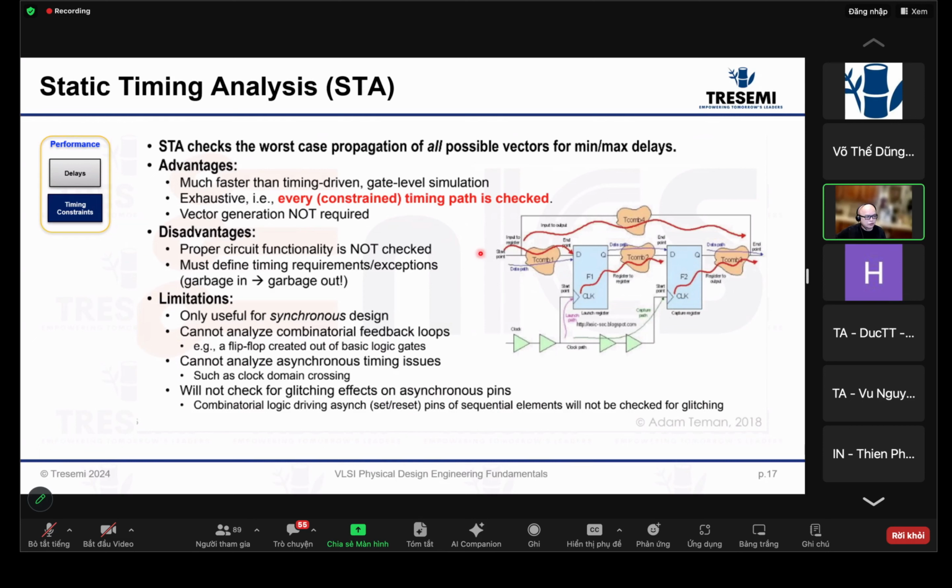So it's very important to check the quality of the constraints going in. While we said it is the most complete, as I mentioned, there are different behaviors that need to be checked by, say, dynamic simulations, and all the asynchronous glitches and everything that we need to verify in tools for CDC, clock domain crossing checking, and RDC, reset domain crossing checking. But you're not going to worry about that in this basic class.